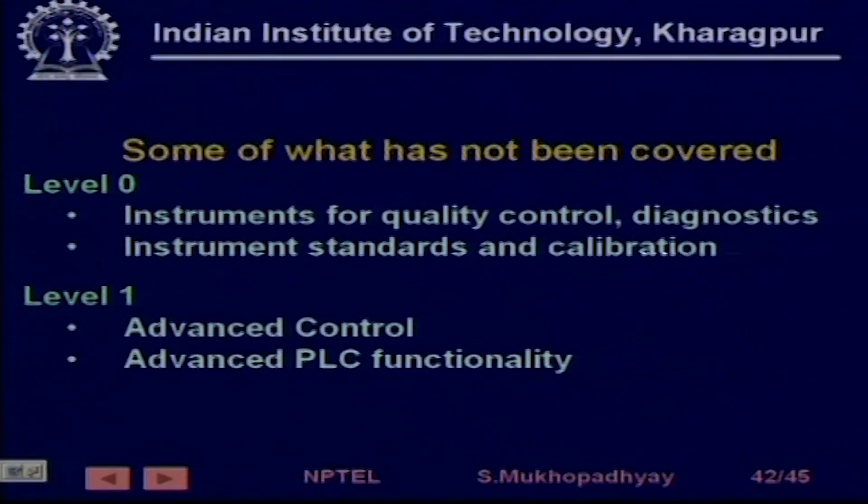Similarly, in terms of control, while we looked at the PID controller and some of the standard process control architectures, there are some advanced controls which are gradually being applied in processes and manufacturing. We did not discuss them, like nonlinear model predictive control. The PLC treatment was also kept more or less to the standard techniques. PLCs have several programming languages, so we did not discuss all of them. We only discussed the relay ladder logic in detail, and then the sequential function chart in some detail.